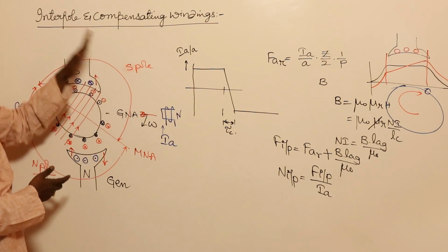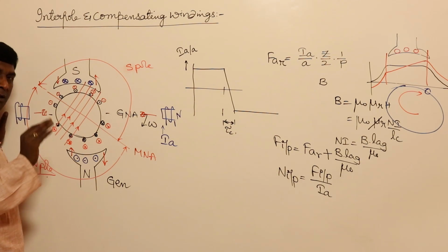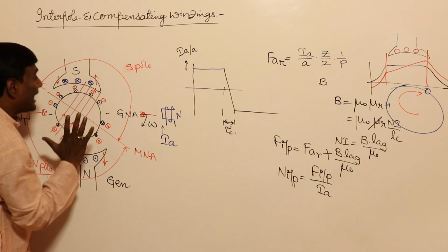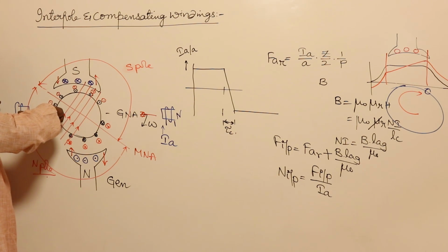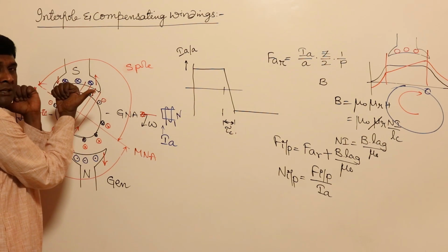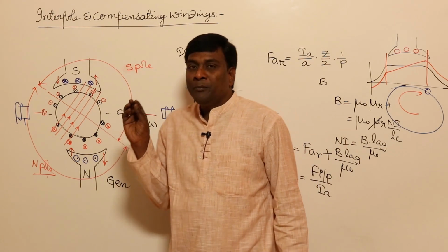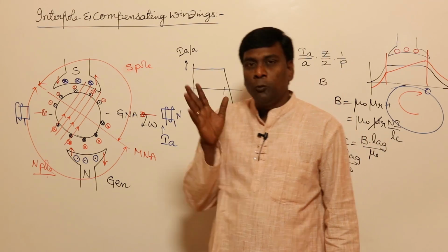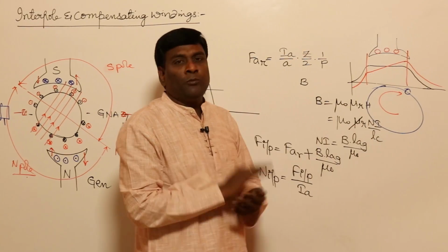Flux variations are going to happen like this. In order to remove this, if I can have, for example, because of the load currents, armature MMF is this, compensating winding MMF is this, cross here, dot here. The moment load is connected, the compensating winding will come, such that both will be compensated. Getting my point, right? So the compensating winding will try to compensate the cross magnetizing effect under the pole shoe, such that these variations will not happen.